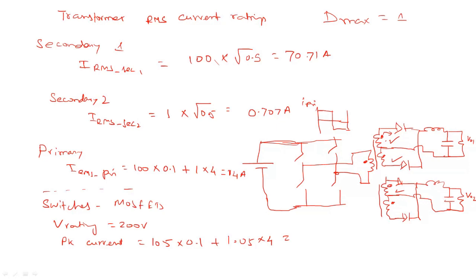I'm sorry. Well, this is just the load current component peak value, and it is given in the problem statement that there is a magnetizing current not to be neglected. It is to be assumed as 5% of the reflected load current component. So this times 5%, times 1.05, is what gives the 15.435.